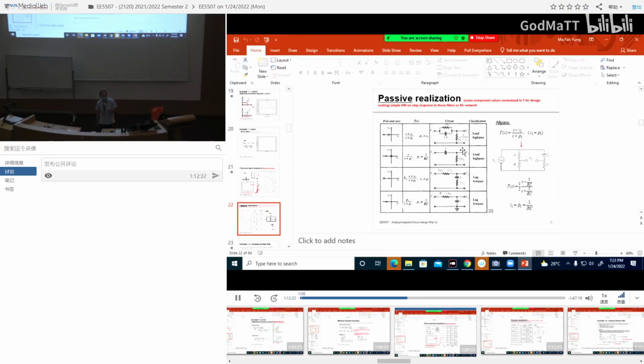Okay, so you can see the problem straight away, right? The IC technology is 2D or 3D? It's a lot of 2D. It's planar, right? So you cannot build a 3D core, not possible. But you can build a 2D core. But the 2D core is not a very good inductor.